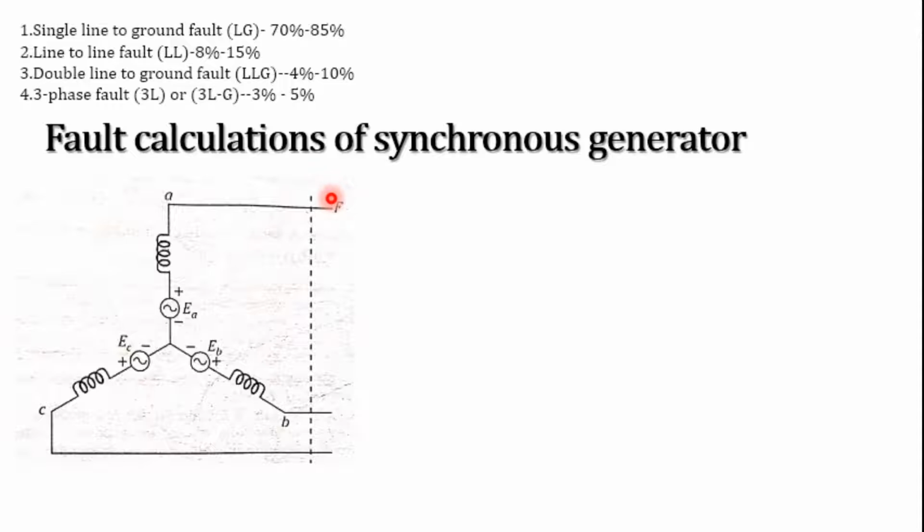Hence, in this condition, the current of a given sequence produces a voltage drop of the same sequence only, meaning the sequence impedances are uncoupled. It does not depend upon the other phases, since the alternator generates balanced voltage only.